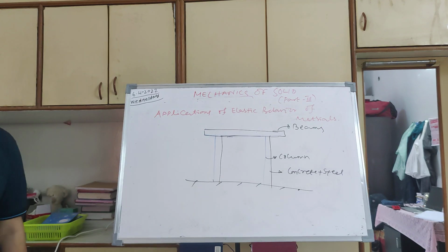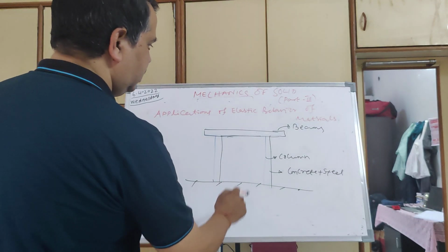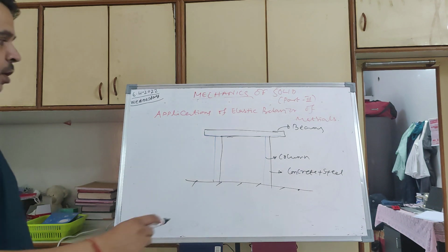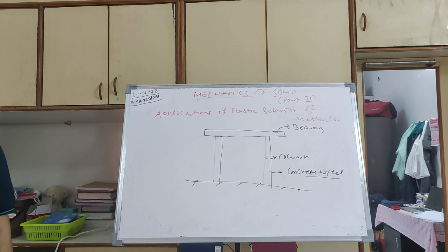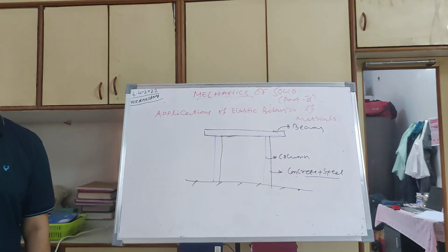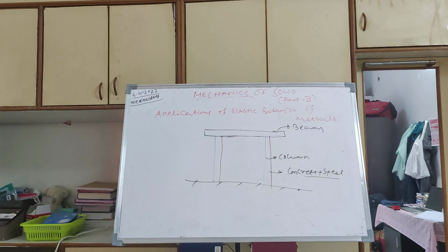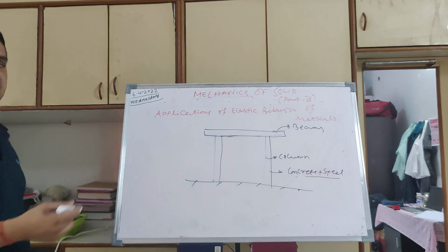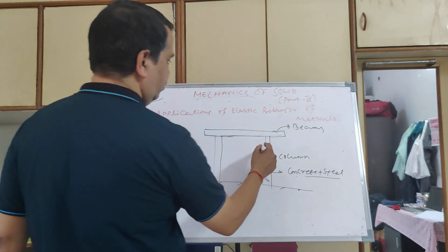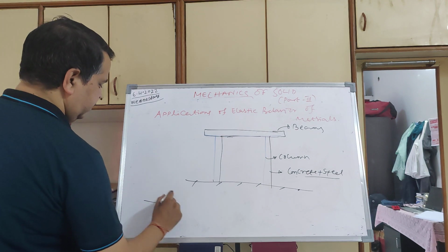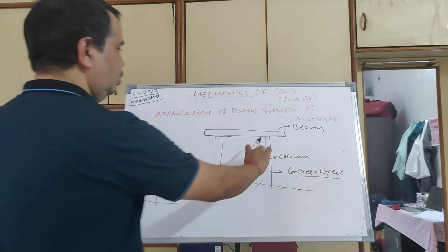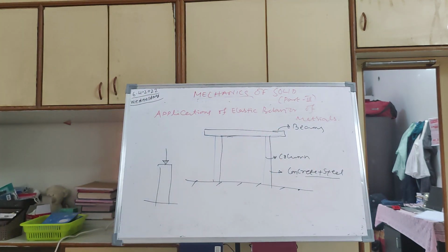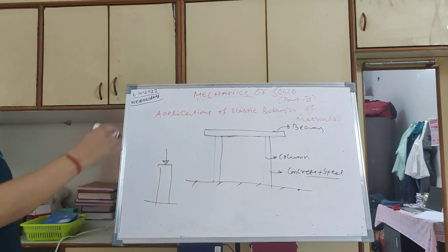So the horizontal members are beams. The vertical members are your columns. The column is made of concrete plus steel. So for any building design, you need to know what the structural material is made of. If it is made of concrete plus steel, then what is the strength of that? Like this column, what kind of load is it taking? If you take a free body and remove the top beams from it, it is taking some kind of compressive load.